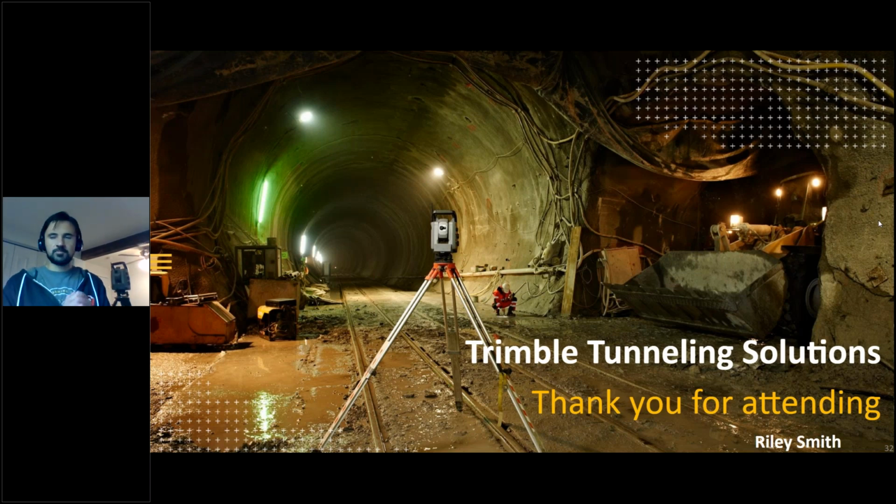With pipe jacking, long curve pipe jacking, you've got these sections of tunnel that are being built around a curve, and in TBC, the simple way to put it is you can design and input any of that data from the official design for that tunnel to do the data prep. Just like we were doing today, you can input the alignment. You could import it from a CAD file, so if your alignment came in from DXF, you could import that, and you can define the shape of the tunnel, no problem, and all that information.